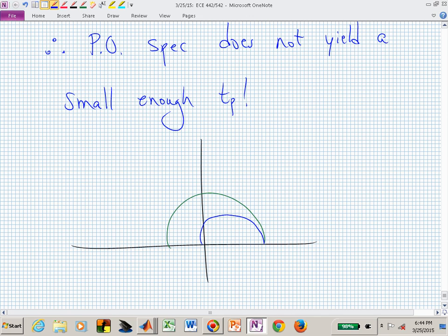Green is thumbs up, blue is thumbs down, and I want you to give me green or blue, which has the least percent overshoot. On the count of 3. Green is up, blue is down, and I want less overshoot. 1, 2, 3. So you need a zeta that's bigger, which is closer to the real line. So that's the blue line.